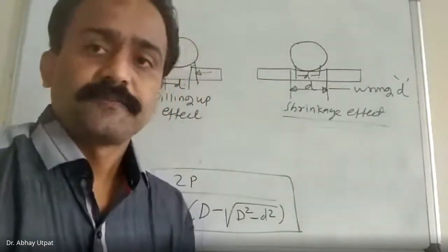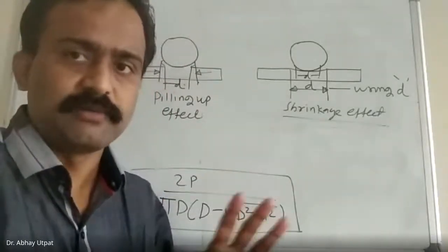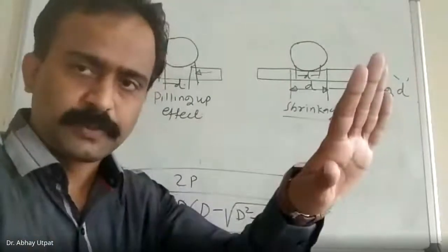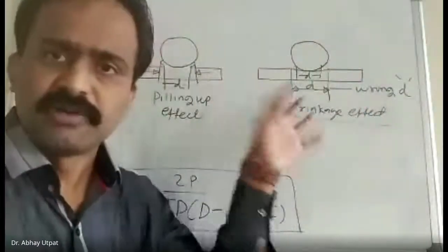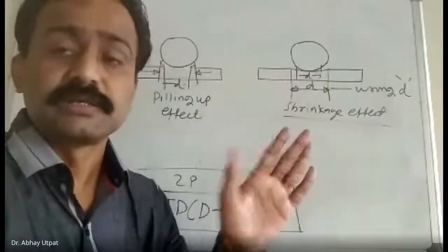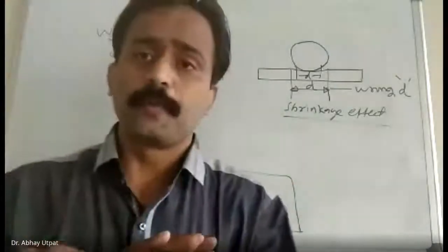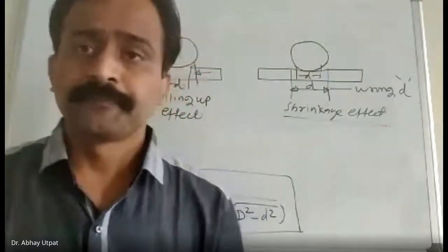Now friends, with this much large size ball, there are some precautions while we are carrying out the experiment, and it is applicable to all types of such experiments, maybe tensile test, impact test, compression test, fatigue test, grip test, hardness test. Your surface should be very clean and neat. It should be free from oil, dirt, etc. That is the primary requirement.